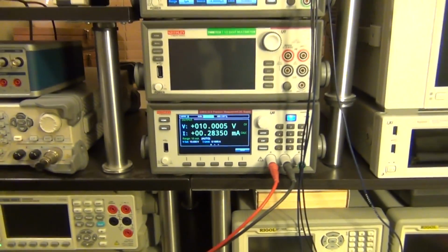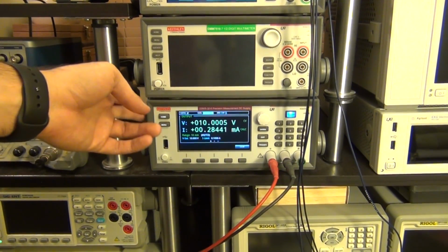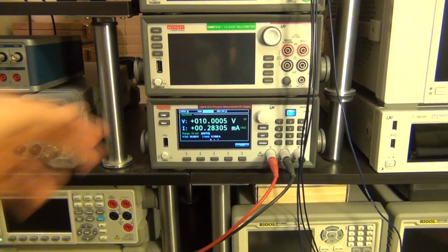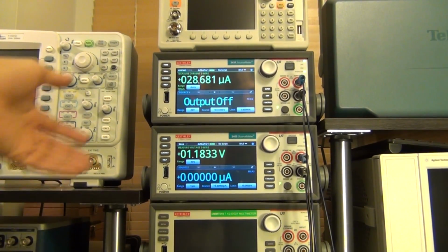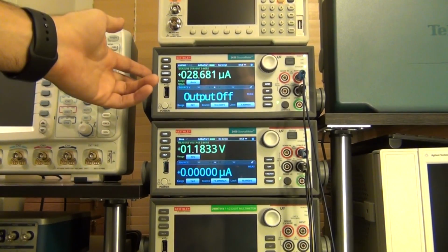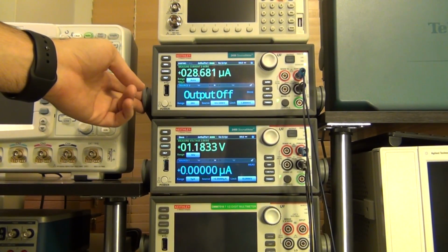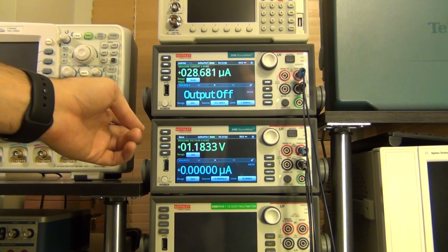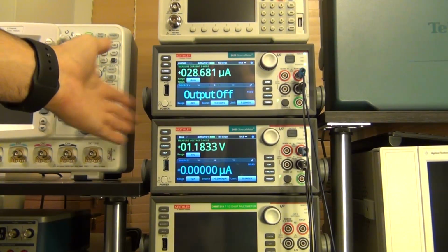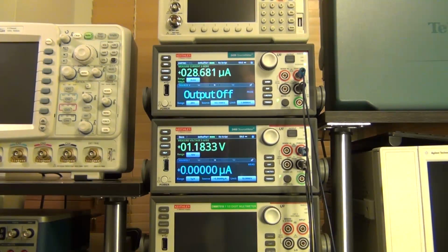And for that, we're going to use the Keithley 2280S-32-6 as our power supply. This is what's going to give us the 10 volts on our inverter. And of course, for sweeping the input and output, we're going to use pretty much the industry standard Keithley 2450 at the top and Keithley 2460 at the bottom. The 2450 is going to apply the gate voltage at the input of the inverter, and the Keithley 2460 is going to monitor the output voltage. And we're going to use the KickStart software in order to do this sweep and capture all the data. So let's move to the KickStart software.